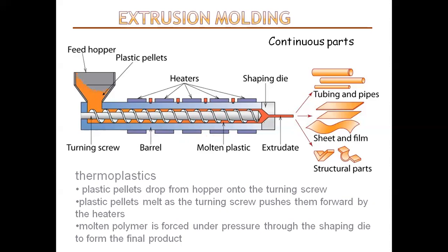At the front of the barrel, the molten plastic leaves the screw and travels through a screen to remove any contaminants in the melt. The screens are reinforced by a breaker plate, which is a thick metal plate with many holes drilled through it.